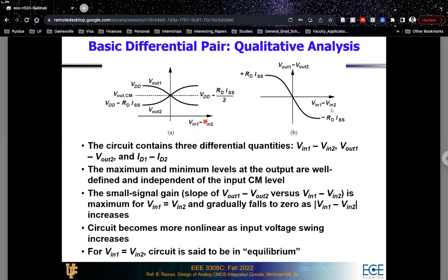We know that in the real world, differential amplifiers are not ideal. And in that case, you might have something called an offset voltage. And you are seeing that as part of your lab 6 experiments, that even if you apply the same Vin1 and Vin2 in terms of DC, the DC values at Vout1 and Vout2 may not be exactly the same.